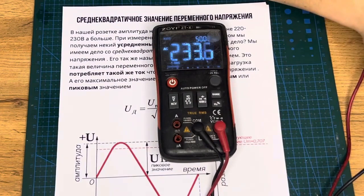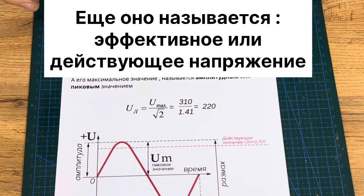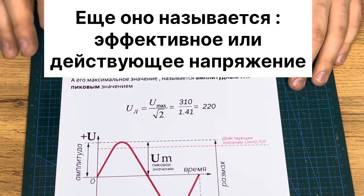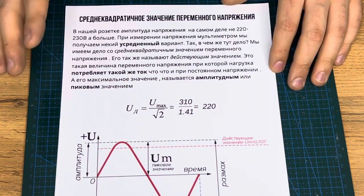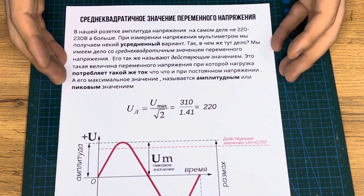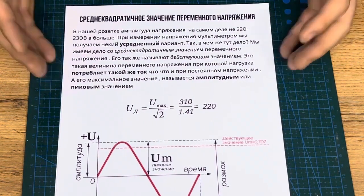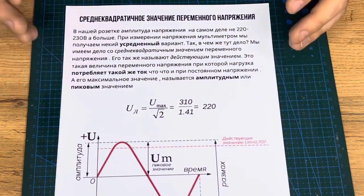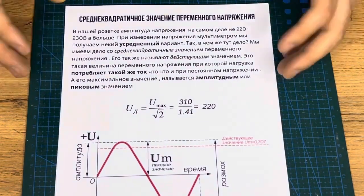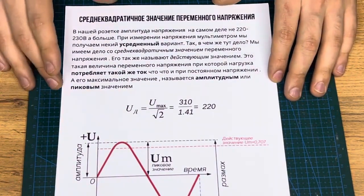However, guys, this value is what's called the root mean square value, also known as the RMS value. The root mean square value means that the tester automatically multiplies it by a certain coefficient. I'll tell you right away, 0.7. This is the coefficient that's multiplied. So the tester does not show you the true value of the amplitude of this voltage. But what is the root mean square value? It is a bit tricky to understand, guys, so I'll try to explain it in simple terms, right on my fingers, because the explanation is a little complicated.